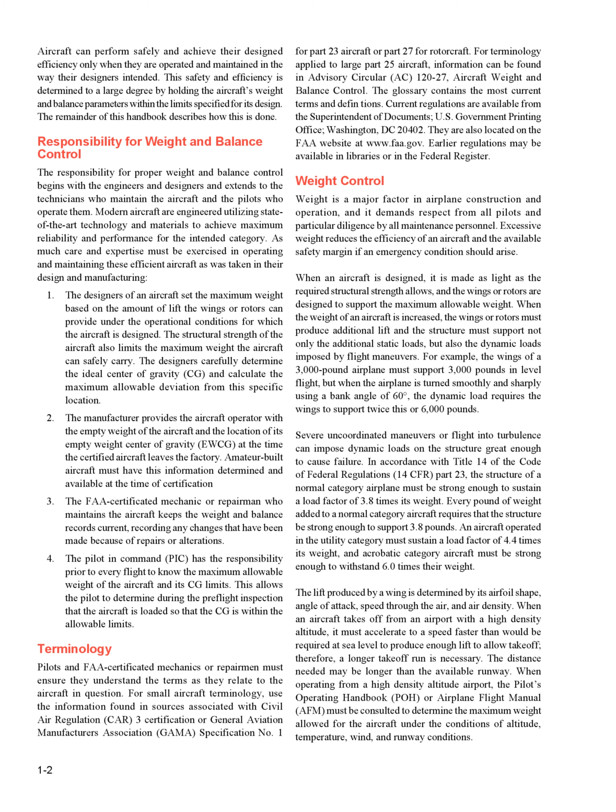pounds. An aircraft operated in the utility category must sustain a load factor of 4.4 times its weight, and acrobatic category aircraft must be strong enough to withstand 6.0 times their weight.